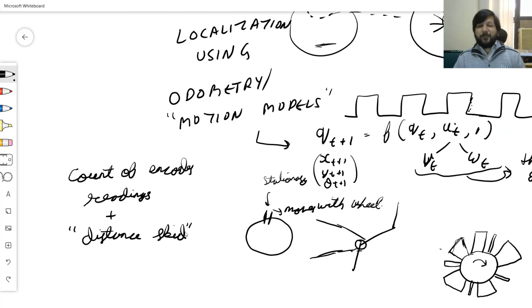And practically what that means is when we use encoders with our indoor robots, we make sure the wheels are extremely high quality rubber, so that they don't skid at all. The rubber quality has to be extremely good so that there's absolutely no skidding. And the resolution needs to be extremely high.